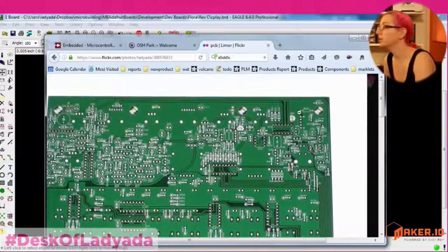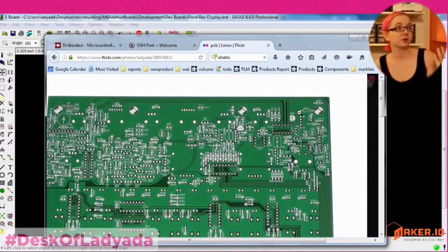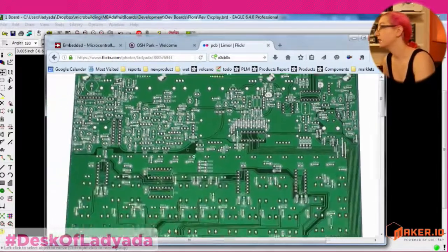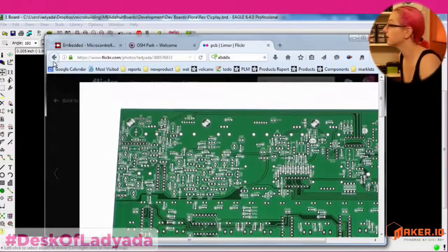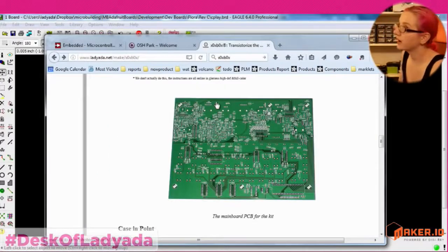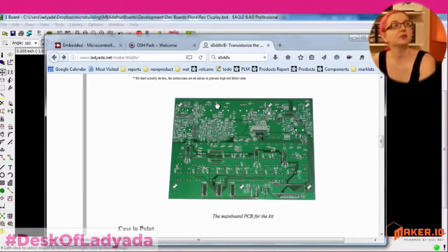But because the PCB size was fixed by the enclosure, we picked components based on that, and that can matter for potentiometers or buttons. They have to reach through the enclosure. The enclosure has to have molded parts for it. So it is something you have to think about. As you're doing your first design, don't worry about the enclosure too much. But as you're getting into your second or third prototype, you're going to definitely want to have a 3D printed enclosure.